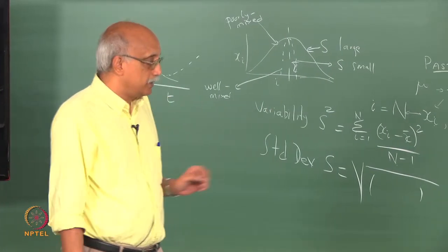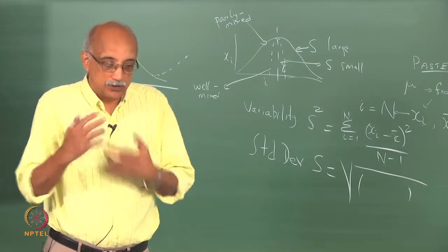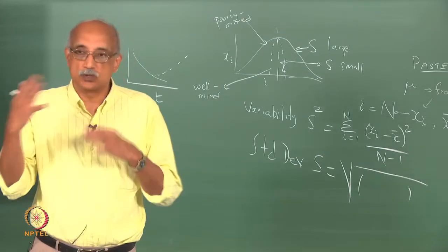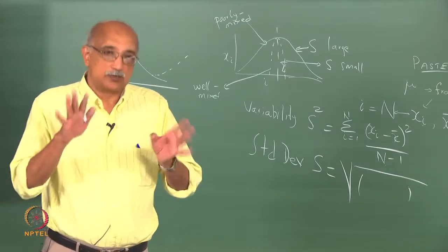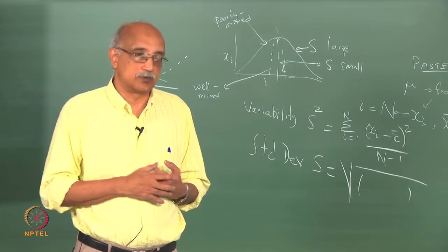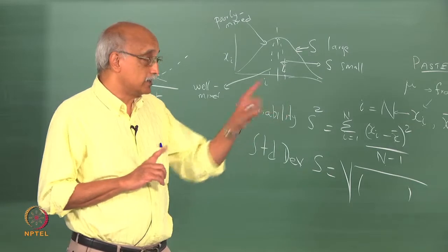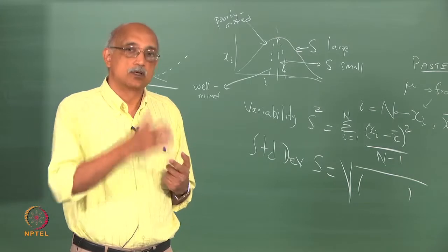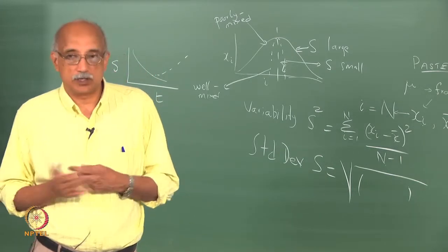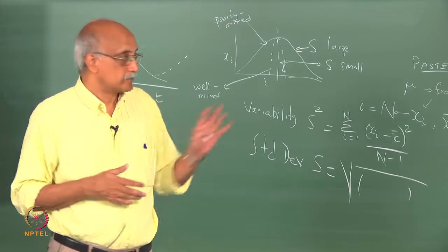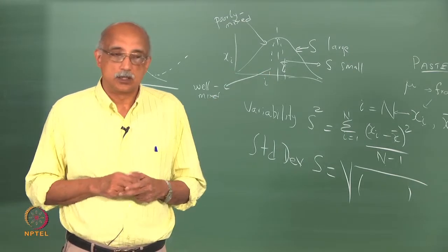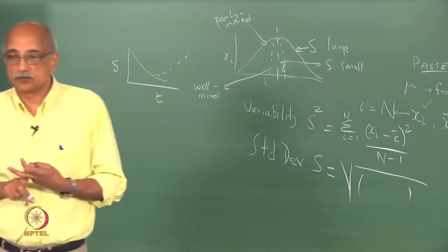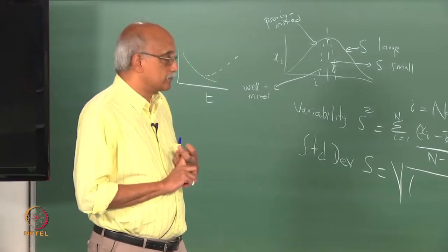For example, this may be the behavior in a simple kneading type of device, whereas if you did the same kind of thing in a centrifugal tumbler, you may get very different curves. You may get a very different slope of these curves. The qualitative behavior will still remain the same. You will still see initially a steep increase in the mixing effectiveness or mixing index, but eventually you will see an asymptotic behavior. So that qualitative nature will not change, but the actual magnitudes will differ depending again on the equipment that you use for the mixing and the properties of the material that you are mixing.